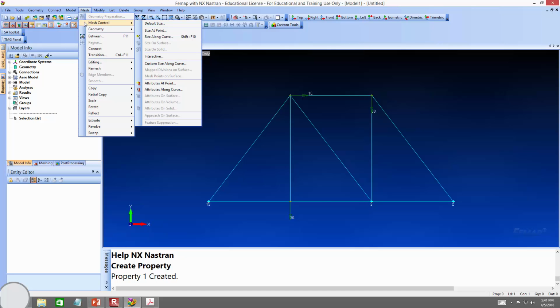If you just let FEMAP do what it wants to do, it'll come up with a mesh that might make sense, it might not. You have to understand the finite element method is meant to analyze complex stuff. It does the best it can, and in many cases, it does a good job. But you all need to have the ability to restrict that mesh into a form that you want.